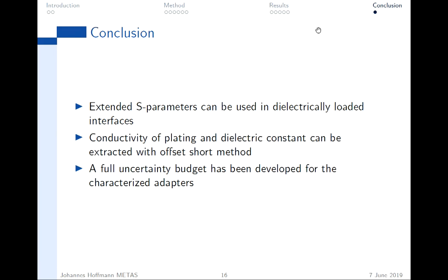The extended S parameters are S parameters in an arbitrary field. And this arbitrary field is defined by forward and reverse operation. So basically that's what they are specific to. They can be the same if you have, for example, a plain transmission line. This forward field can be the same as for a pseudo S parameter mode, and then they're the same.